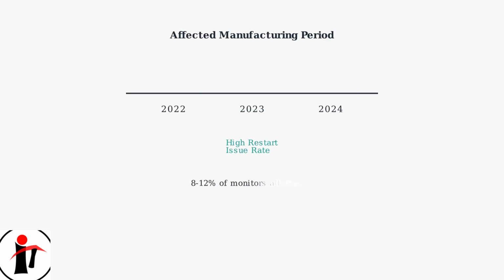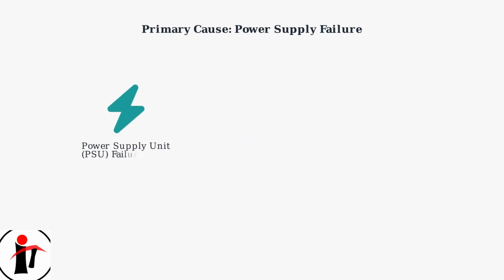This issue has become increasingly common, particularly affecting Sceptre monitors manufactured between 2022 and 2024. The primary culprit behind these restart issues is power supply unit failure, specifically capacitor degradation. This accounts for 60 to 70% of all restart loop cases.